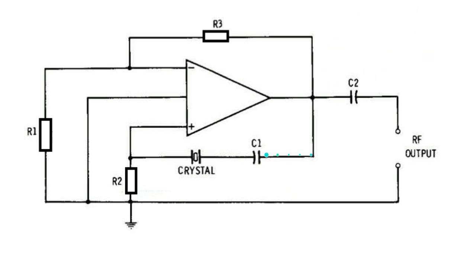Capacitor C1 is utilized simply for blocking the DC content, with a capacitance whose value is specifically selected for low reactance at the crystal frequency. The input ground of the op-amp, which is common ground, is connected directly to the circuit ground, as indicated in the diagram. The circuit can also be seen having a negative feedback loop, created using the resistors R1 and R3, which constitutes a signal voltage divider network.